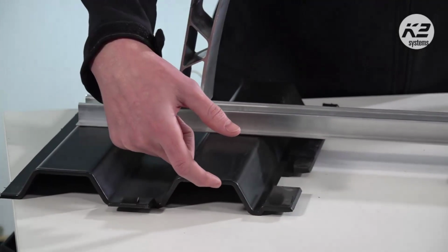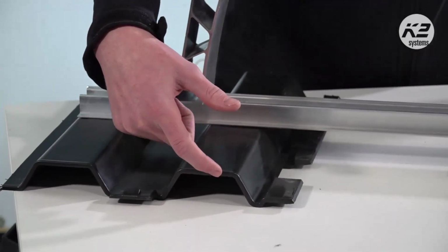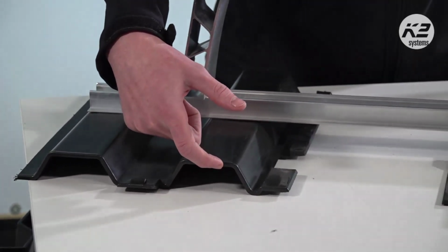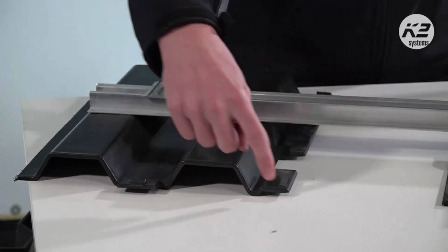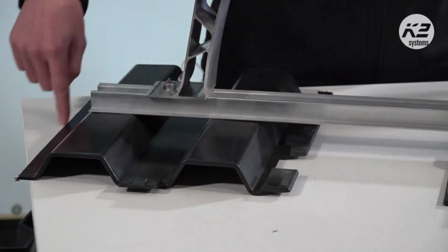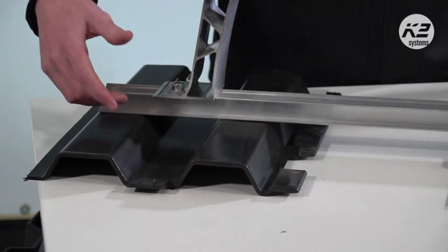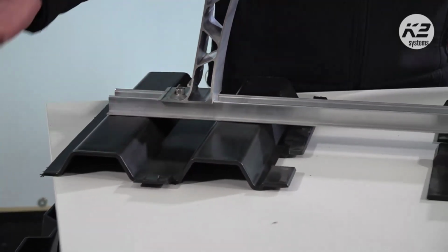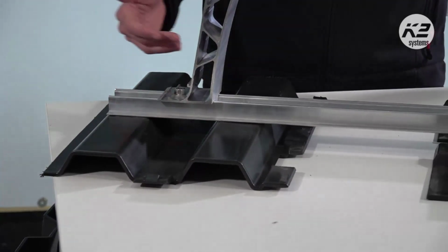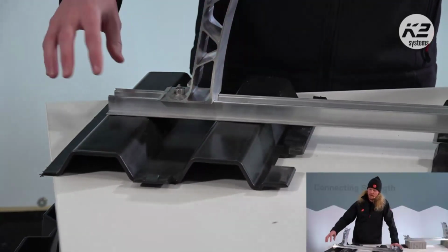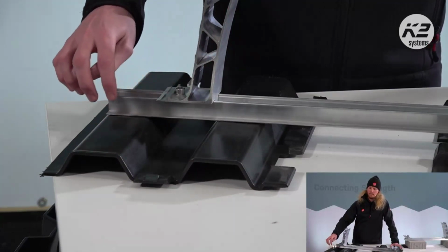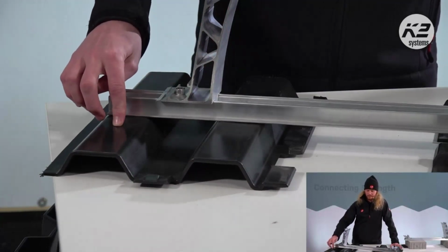And so whether it's gravel, which I think is usually about 1.5 tons per cubic meter, we know the area of this mat, we know the thickness of it, so we have a volume of gravel. We can then calculate a rough equivalent of how much ballast or how much weight this one mat represents.